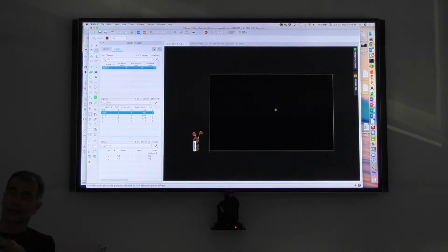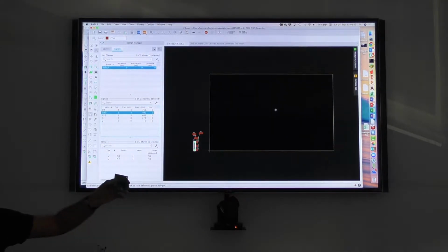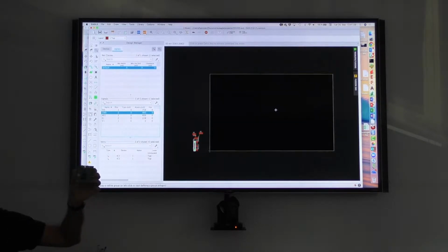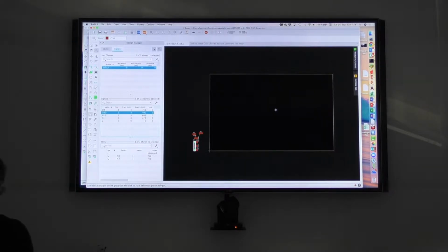Of course, there are some standards all the board manufacturers use, but if you think of components like this black square one, that's a BGA, a ball grid array. If you look onto the board, you don't see connections, no pins, no pads, because all the connections are beneath the case. And this one has about 250 connections beneath it. If I have a BGA in this size as the board is, I have about 1500 connections. And if all the connections are used, then it's really critical how the layer setup is.